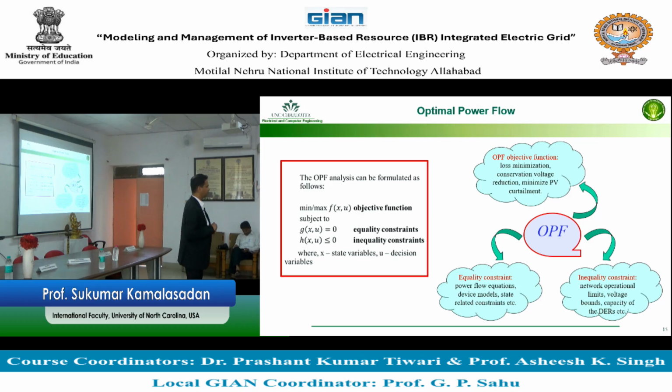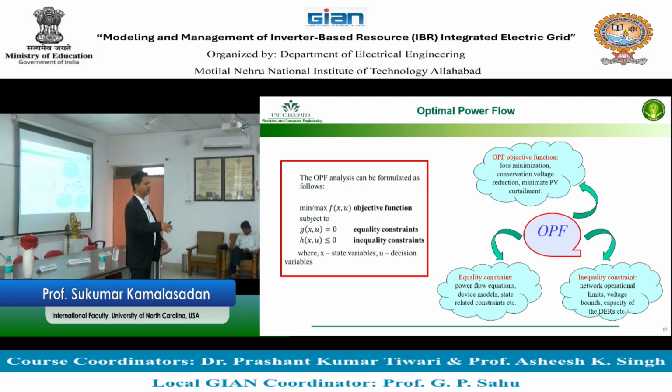For example, in the power electronics world we say output power is equal to input power, DC is equal to AC, a 1-to-1 ratio, with nothing lost except the switch losses. We try to neglect those or make them small. That is an equality constraint. You can make sure that the DC power is in a 1-to-1 ratio with the AC power without having to make sure that you cut.